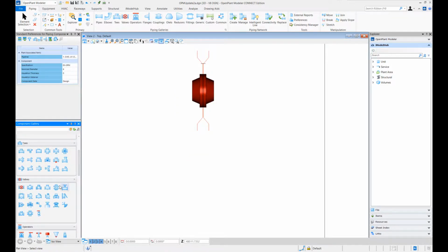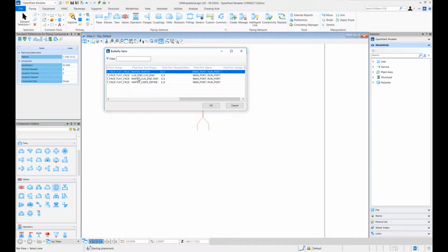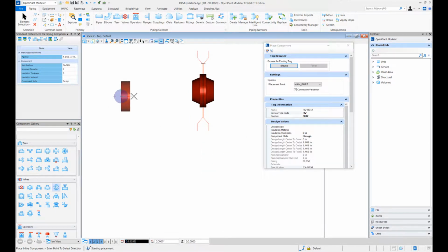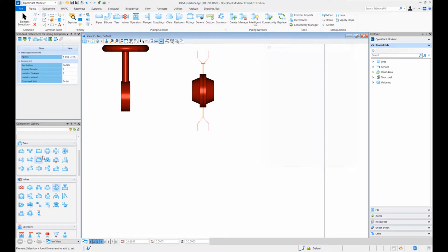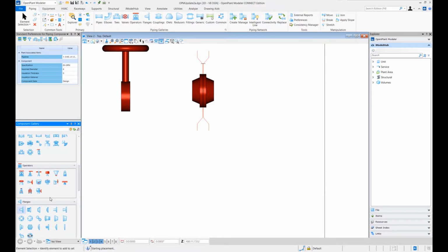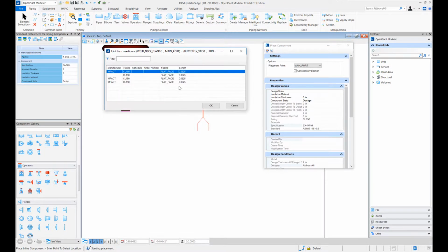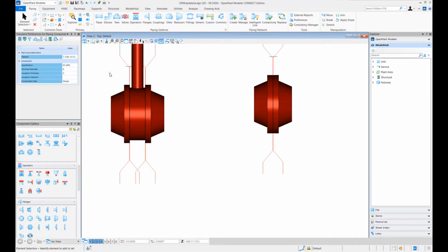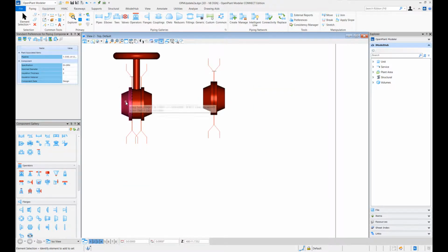Next, we'll place a few wafer ends. So this is a regular wafer end butterfly valve. And let me just place it here. And now I'll connect some mating flanges with this valve. It asked for gaskets and a set of bolts, which are partially threaded through bolts. So when I was placing a wafer end, it asked me for gaskets on both the ends and just one set of bolts, which are through bolts, at the time of completion of the joint.